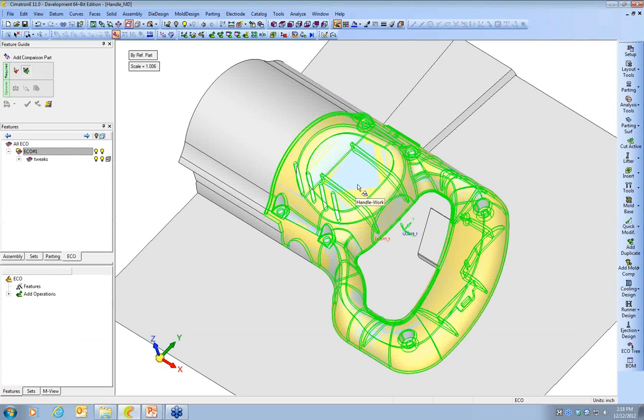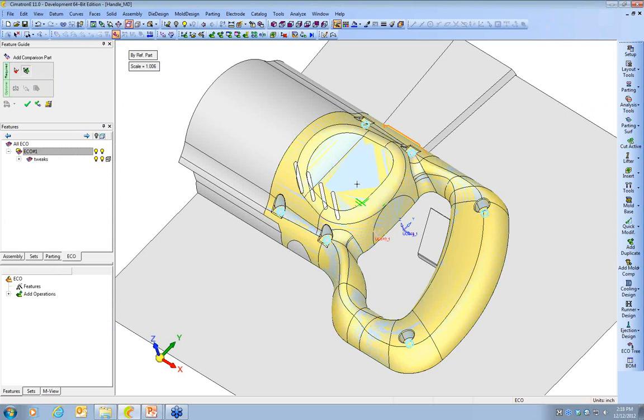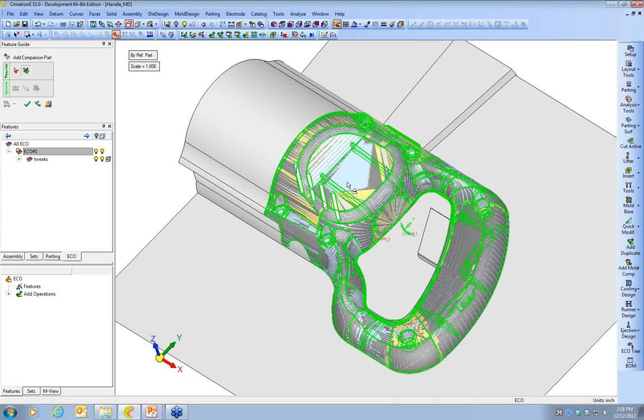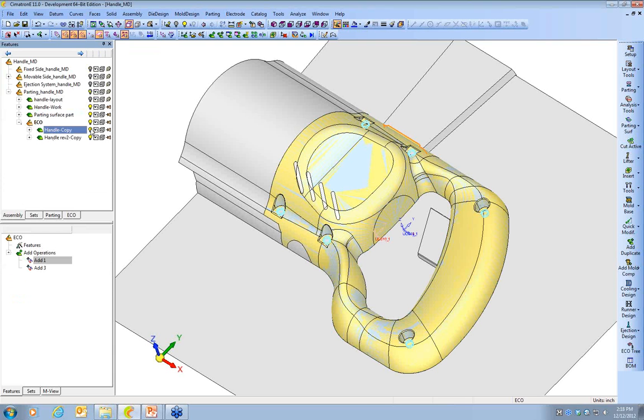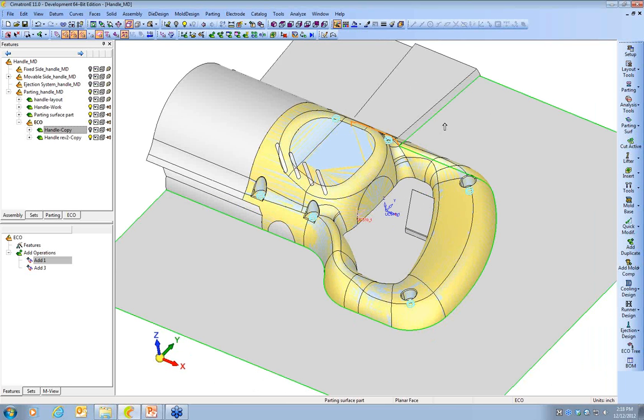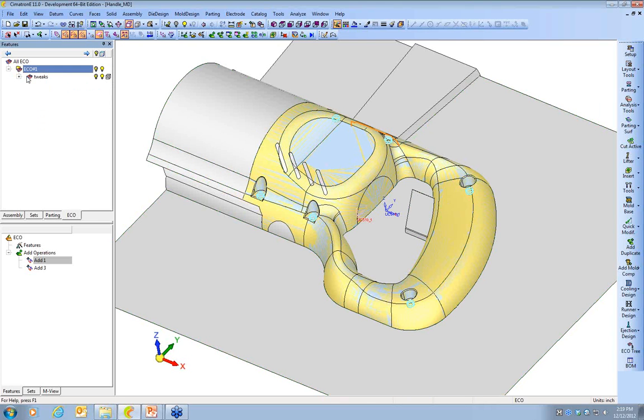So let's add this one into the assembly. And again, we'll just use the work part to supply the location and the plastic shrink value for it. So in this first example, this first change, what I want to talk about is that top-down approach for bringing the new data in right at the very top step of the design. So because of that, when I do the comparison here, I'm just going to use the old and new customer data files. Nothing about the existing mold design yet.